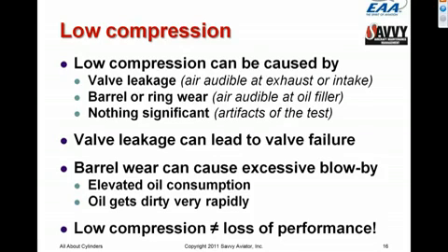So when we're doing a compression test, if the compression number we're getting is low, we want to use our ear and figure out where the air is leaking. If it's coming past an exhaust valve, for example, we'll hear air leaking out the exhaust pipe. And if it's coming past the rings, we'll hear air coming out the oil filler. And in fact, where the air is coming out, which we detect with our ear, is much more important than what the actual reading is.